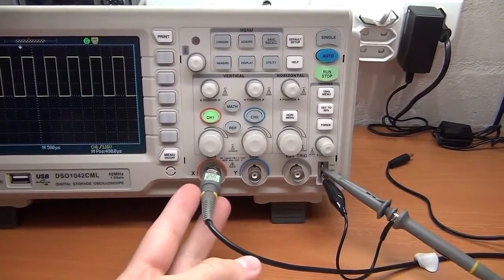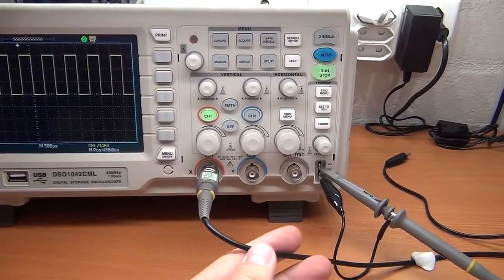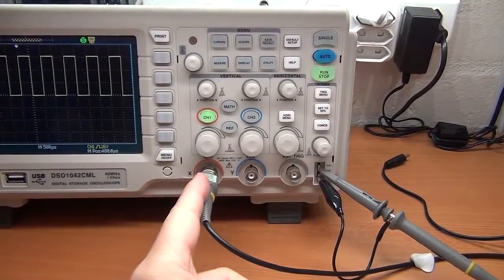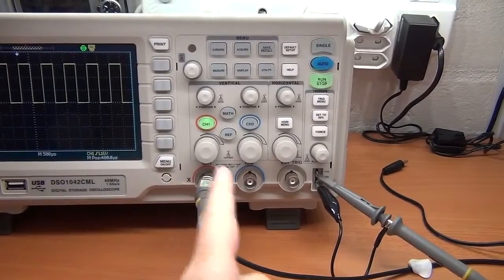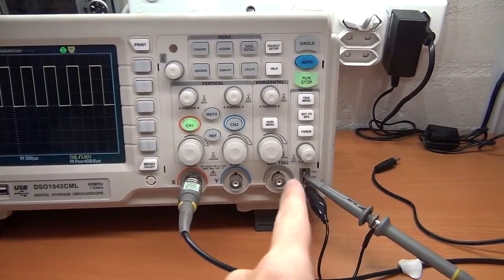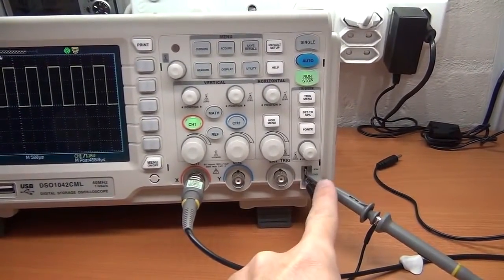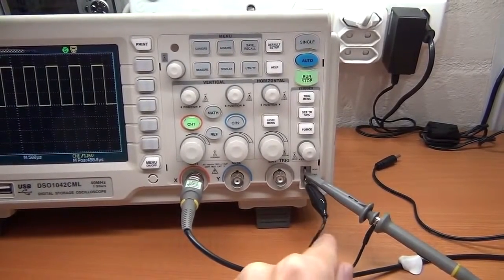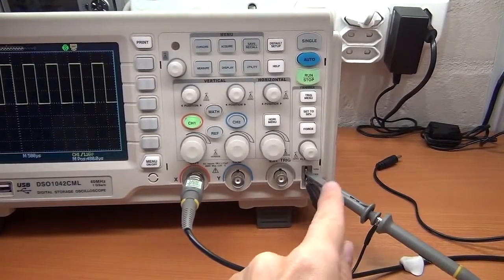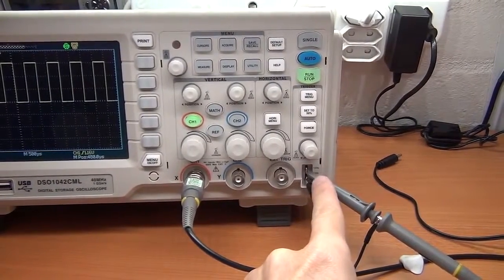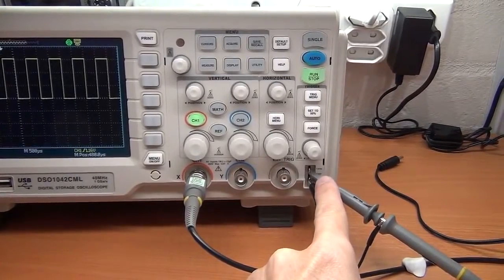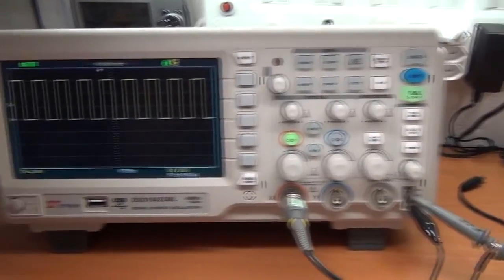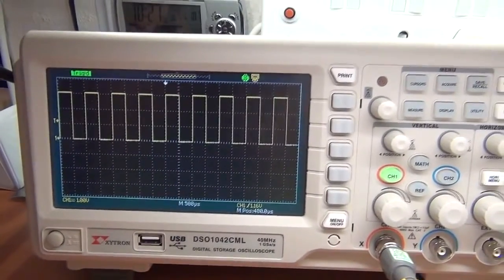But your oscilloscope probe is where you're going to pick up your signal. And this oscilloscope happens to have 2 channels. I'm just using 1 channel, which means we can actually view 2 signals at the same time. Your probe is what you'd connect onto the signal you're measuring. And then you have another lead, which is in essence the ground lead for the signal. So I've got these connected to a reference signal, which you can use to calibrate your probes with and what have you, but it makes a nice easy sample signal on the actual scope itself.